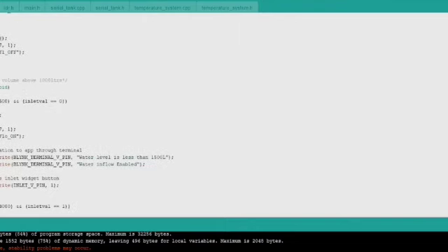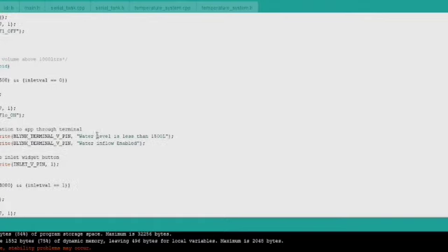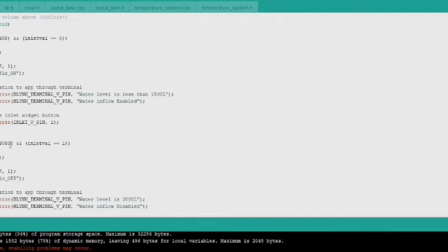The third and last part of our project is about the serial tank. When the tank volume is less than 1500, that is what we have taken in our project. And when it is less than 1000, the inlet should automatically turn on, and a notification should pop up saying the water level is less than 1500 liters, so the inlet valve is turning on. The maximum level is 3000 liters, and when the tank reaches 3000 liters, the inlet valve should turn off. And whenever we turn on the outlet valve, the water should flow in the opposite direction.